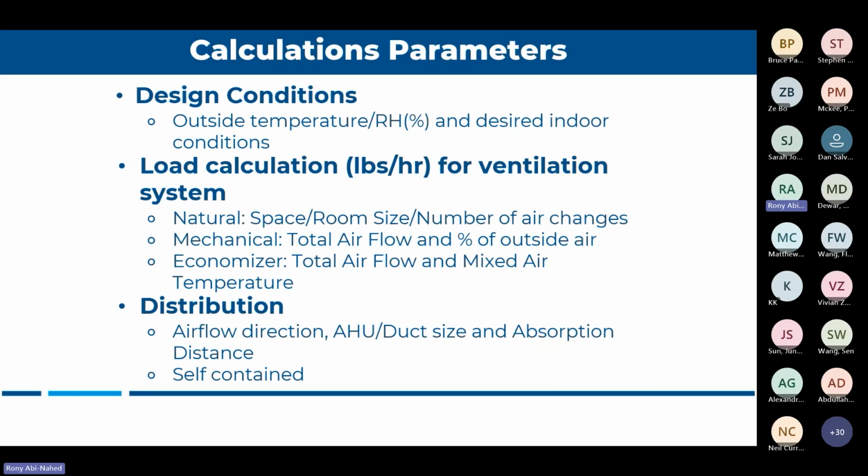So now, if you guys are designing a job, what type of information would Odell need from you to be able to give you a selection and help you design a humidification job? We need to know what your outside temperature and your design conditions are. What's your inside condition that you want to maintain? We need to know what type of equipment you are using.